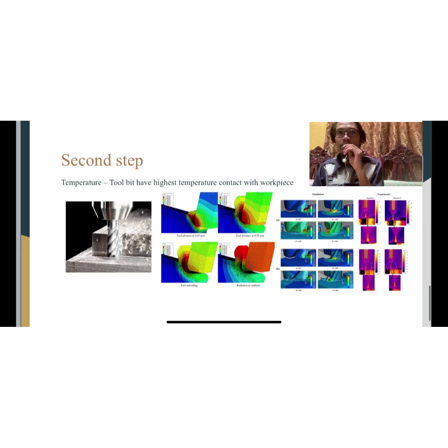The next method is temperature. Temperature is one of the things that happen during cutting between the tool and the workpiece. When the cutting temperature increases, the chemical dissolution of the tool material also increases. By using a developed mathematical model, the wear rate and the temperature can be estimated, but it is hard to predict the wear length and it requires a database of the thermochemical properties of the specific tool and workpiece.